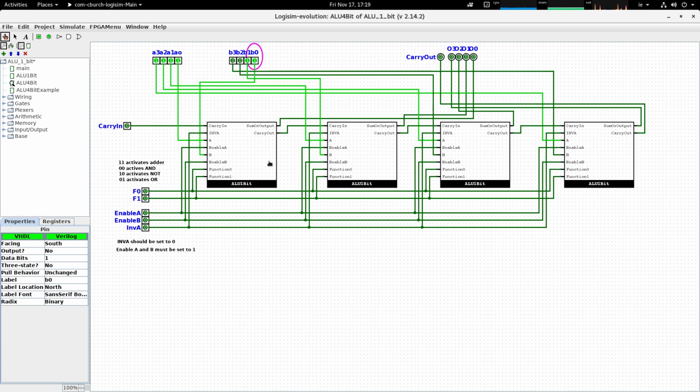Now the type of operation that's done here is known as a bitwise operation. So all we're doing is looking at the first digit of A and the first digit of B and ANDing them together. So if you have forgotten what that means, you should go back to, I think, lecture number 3 and just very quickly review the AND function and look at the truth tables for a 2-input truth table.